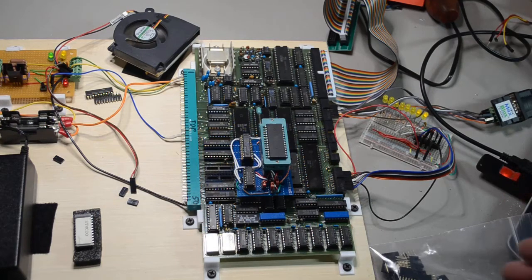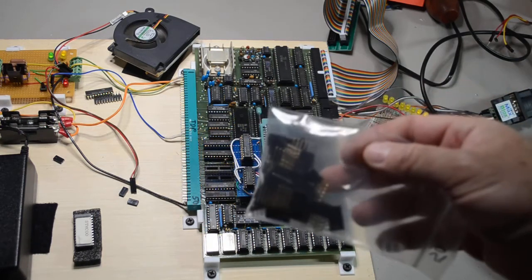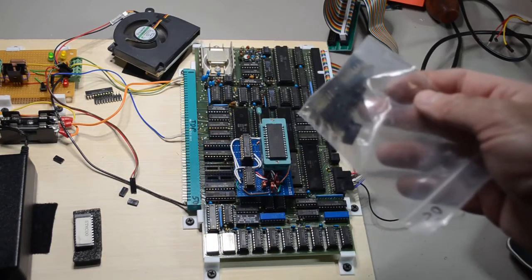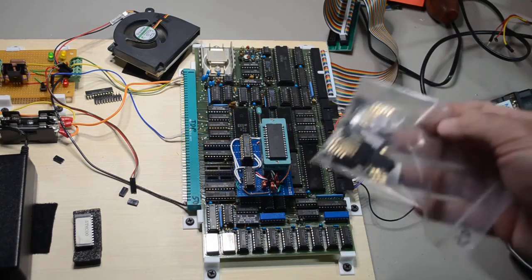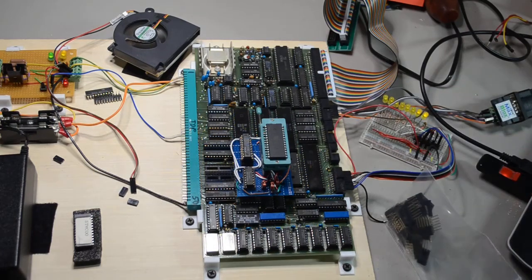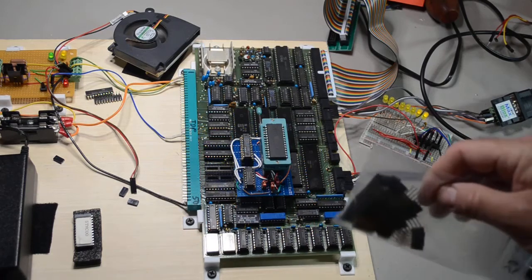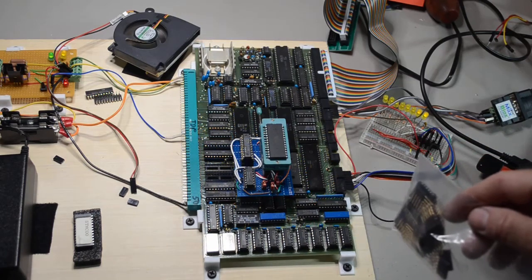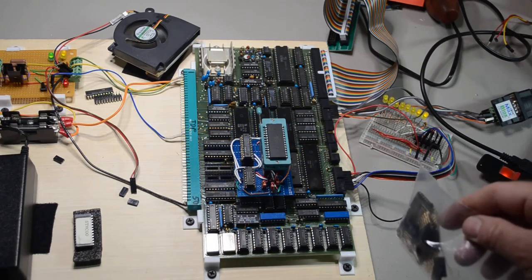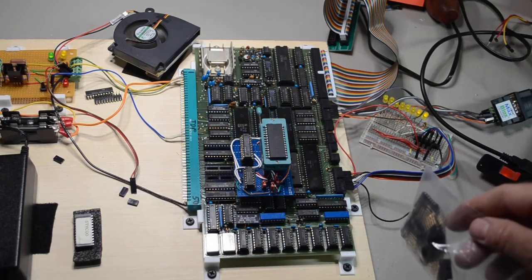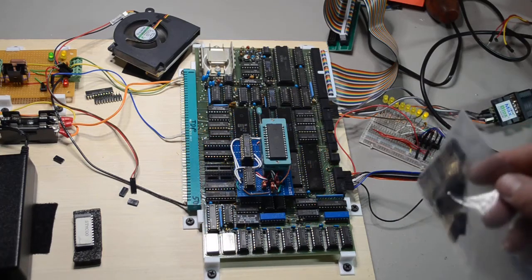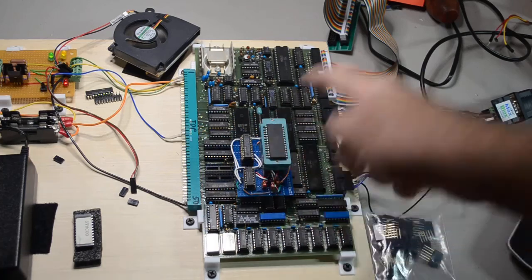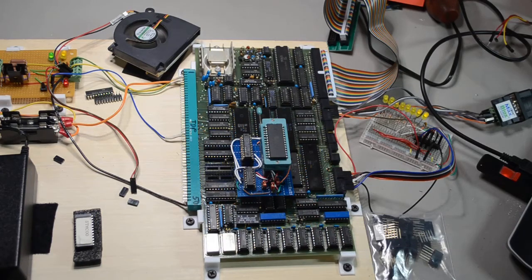Next mistake was thinking that these headers would work as IC sockets, that you could just plug an IC in them and make good connection. No, doesn't work. The ICs don't make a good connection in there. The legs on the ICs are just too narrow. Some of them don't connect at all. Some connect intermittently. So, you know, that didn't work at all. I figured out pretty quickly that I was not getting the signals through to all of the IC chips.